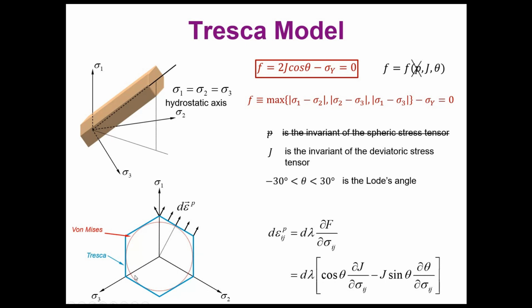But evidently the von Mises stress, because it's a circle, is much more effective in terms of the definition of the direction of the plastic deformation. Unfortunately, for real applications, sometimes we need to use Tresca, because Tresca will give us a better match with the experimental results. But mathematically, the von Mises model is simpler, and sometimes we prefer to get a simple model than a more accurate model, because this model will be more stable.